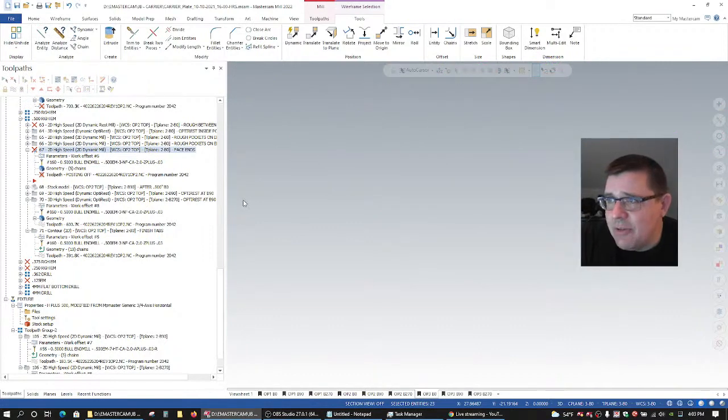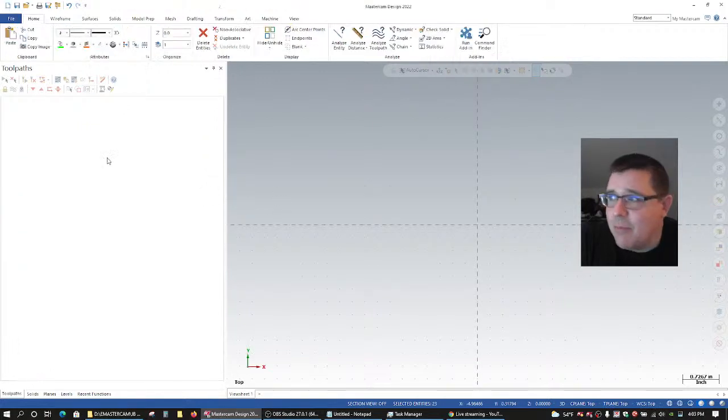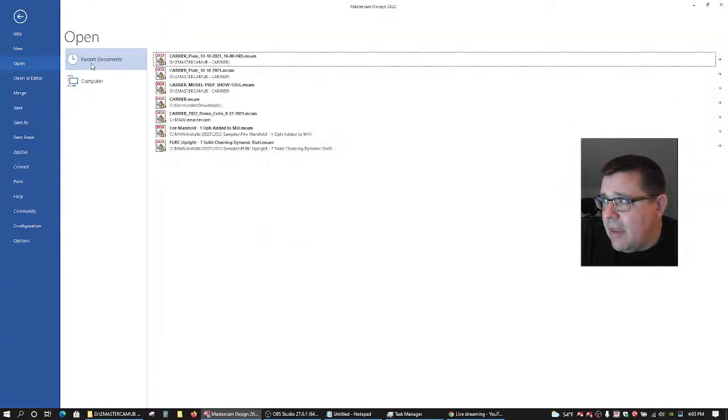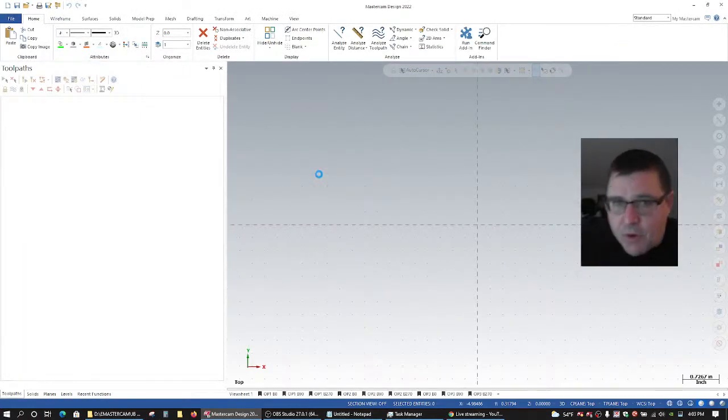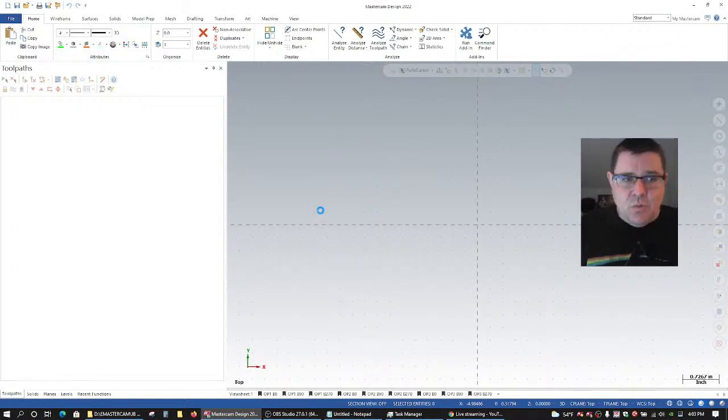And that clears out the Mastercam database. So then I'm starting with an empty Mastercam file. And then I'll do a file open. And we'll open up the version before I ran the repair file function. And this is part of why I gave it a new name when I was running repair file.